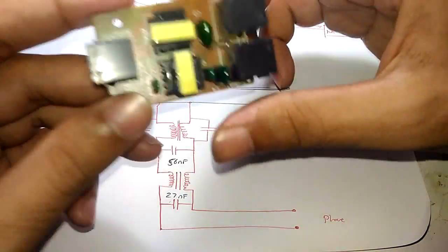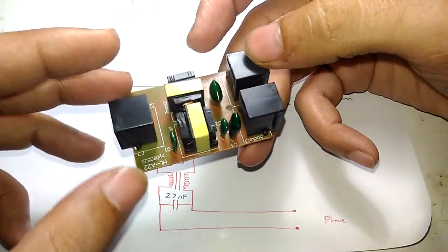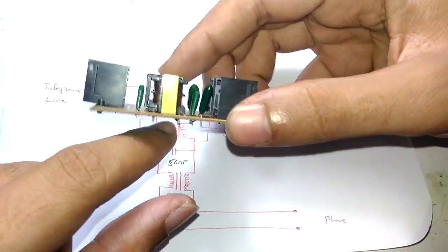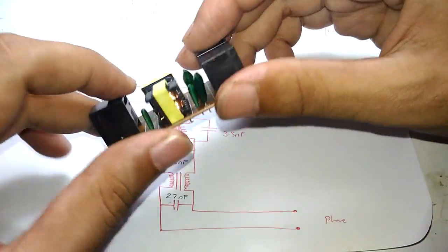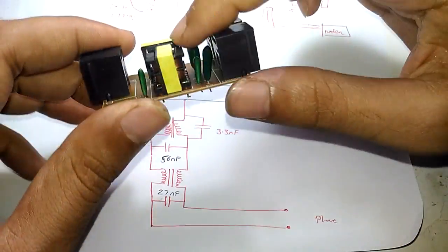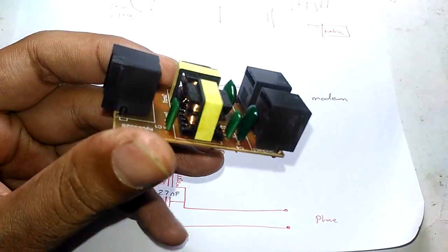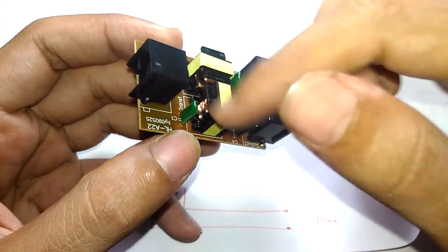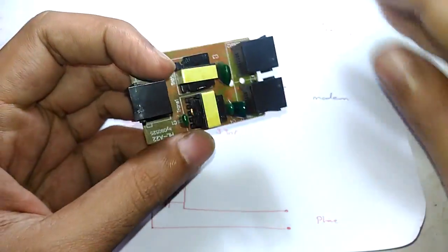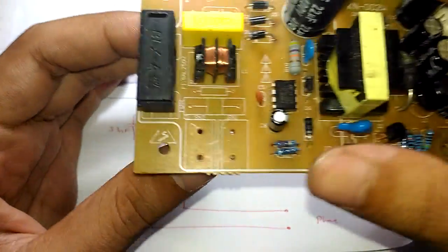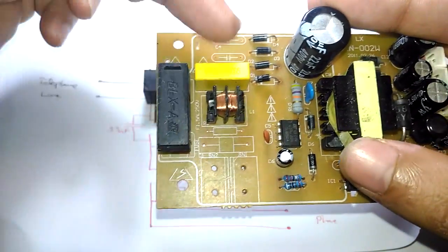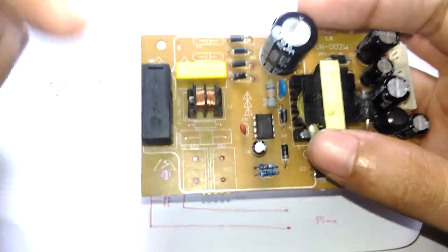As I mentioned in the beginning, these are known as passive filters, because you can see there are no active components involved. There is no transistor, no diode or anything. There is no active electronics involved, and hence they are known as passive filters. By the way, these are not transformers. In fact, they are just inductors wound in the form of a transformer, and they act more like a common mode choke, like the one you find in an SMPS. Not for line filtering, it's also for preventing the high frequency from getting back to the line.